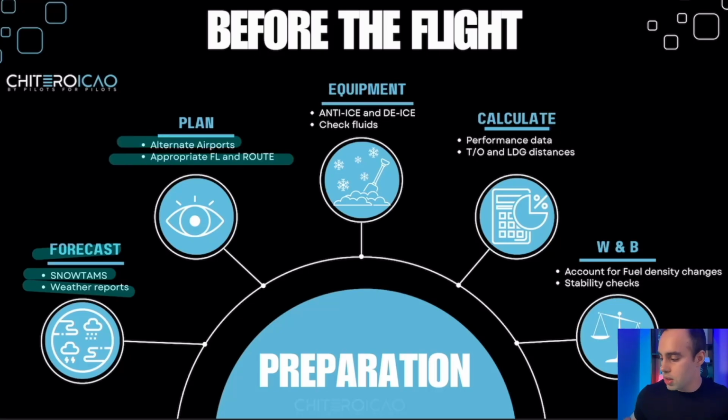First thing, we're going to choose a good alternate. I'm not even talking about the destination here, but about an alternate. The alternate airport needs to be in a better area, so we can land. Especially because some airports close due to weather or snow accumulation, and every airplane is going to have to divert. If every aircraft diverts, they are probably going to the same airport. For example, it happened last year. Midway was closed, everybody diverted to O'Hare, and now O'Hare doesn't have any slots.